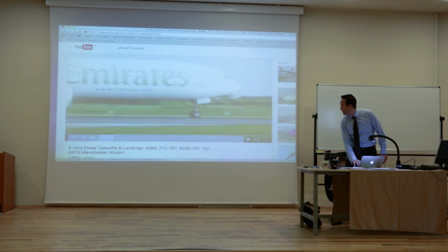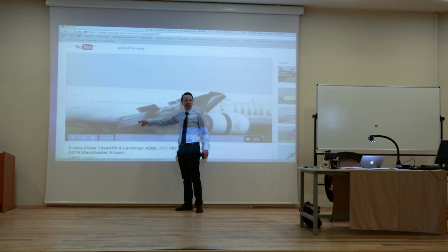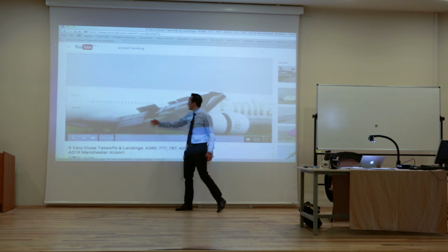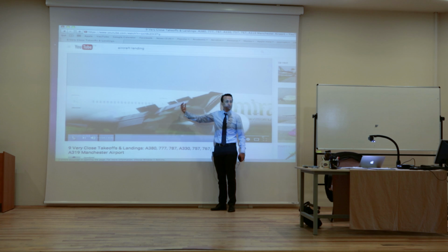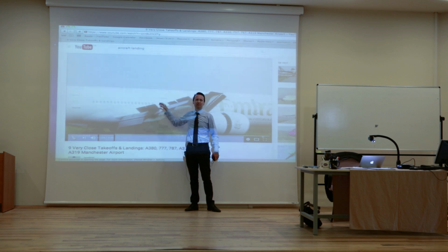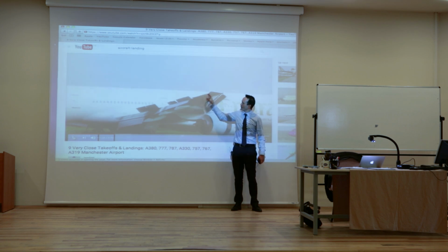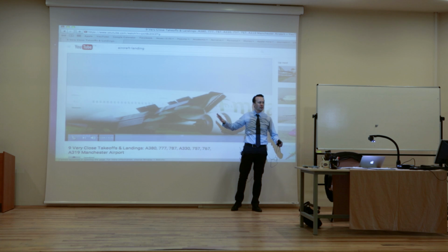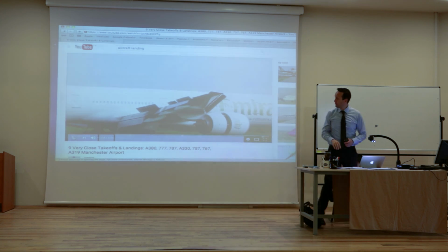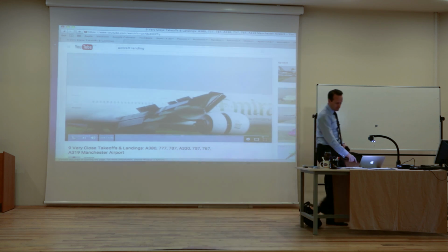That's a Boeing 777, so it's a large airplane. Look at this. Look at the flap. Can you imagine the drag coming from the flap? Look at this one, still flap. Lots of drag. Look at the spoilers. You want a lot of drag, very little lift. Ailerons here. That piece. The rest is just trying to reduce lift. A lot of drag, of course, now. I mean, when it was landing, it wasn't probably that high. Okay.